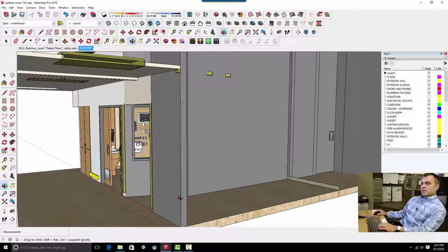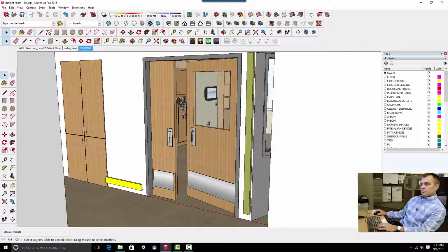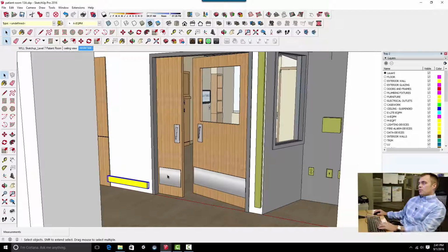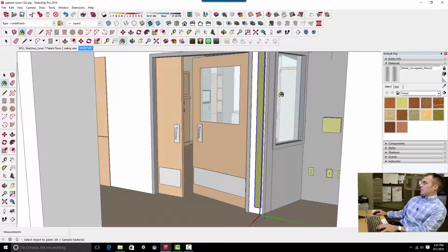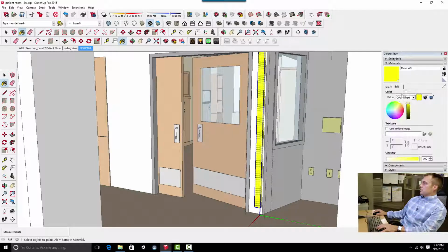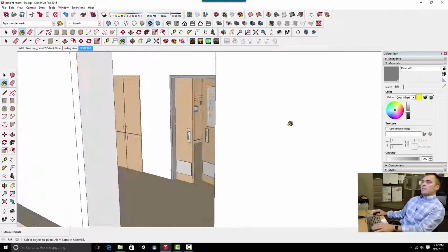Other things that happen is naturally you get some stray objects, or you get objects with materials that aren't as they're really called out in the documents or specified. So we take those examples, recolorize them, and make them look how they are called out in the documents. So this one is supposed to be a gray trim piece. So we'll dial that back and make it gray.